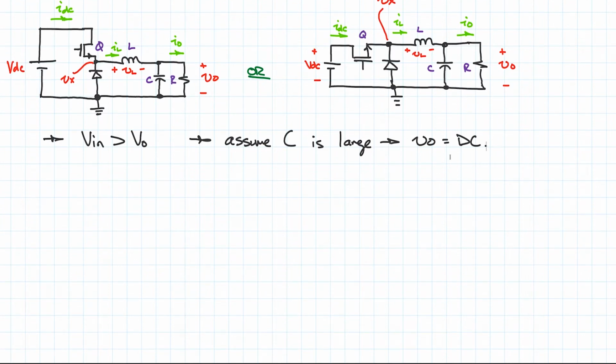So we have here what we call a switch mode circuit, which means there are different operating conditions depending on the modes of how this circuit operates. We forgot to label this: we can write G, and we call G the gating pulse. Every power electronic converter has gating pulses, and gating pulses are how we control the switches. A gating pulse will basically be a square wave like this. When it's high, the switch will be on. When it's low, the switch will be turned off. We're going to use that fact to analyze this circuit.